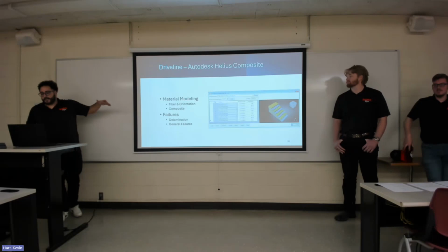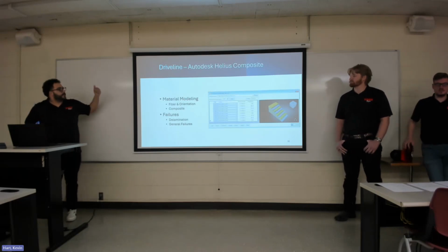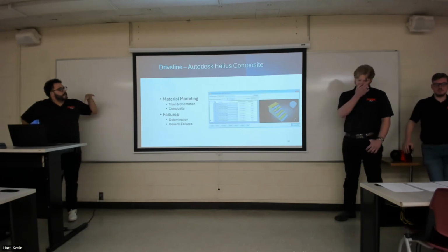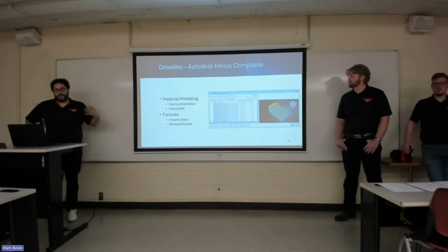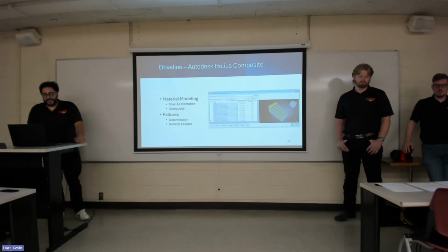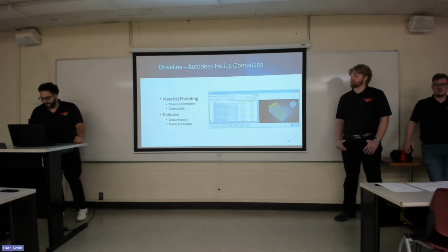And then it also goes into the material modeling. It allows users to define the properties of both the composites, the fiber, and then the composite matrix and the fiber matrix, so how it's actually weaved, and then the type of weave, whether the angles and the amount of weaves you have is dependent on or what sets your strengths. This allows you to determine different failures as well, including delamination between layers using the virtual crack closure technique and the cohesive zone method. It also just goes through a bunch of general failures like the maximum stress criterion, the Tsai-Wu failure, the Hashin failure, and the multi-continuum theory.